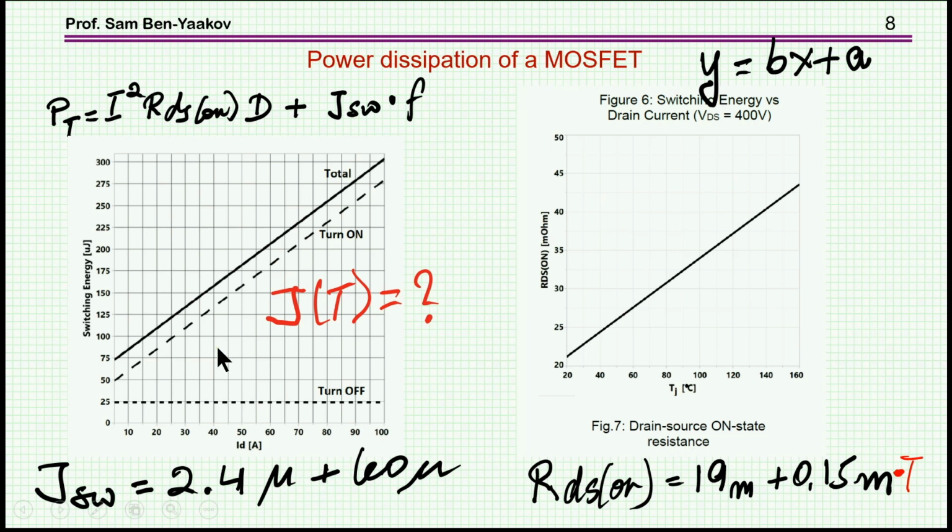And here we see switching losses of the GaN device, the one that I've mentioned earlier. This is the turn-off, this is the turn-on losses, and this is the total switching losses. These are energy per switching, a pair of switching on and off, the total.